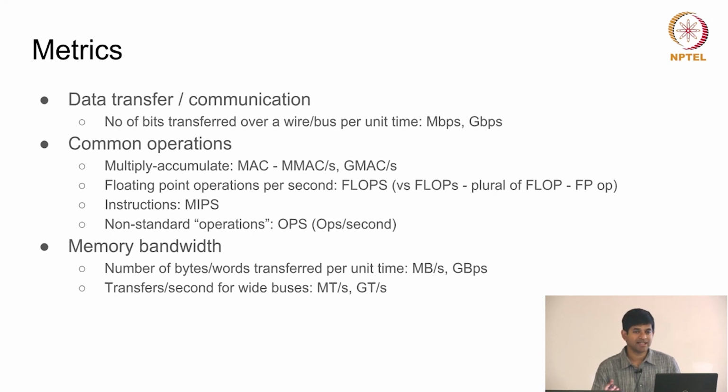Okay, so this is an extreme opposite of the sort of serial bus transfer that we are talking about, where you actually have 1024-bit wide buses. They are used only for very short distance communication, just from one chip to another literally, but you can get fantastic bandwidth in that way. Okay, we'll look at that a little bit more moving forward.